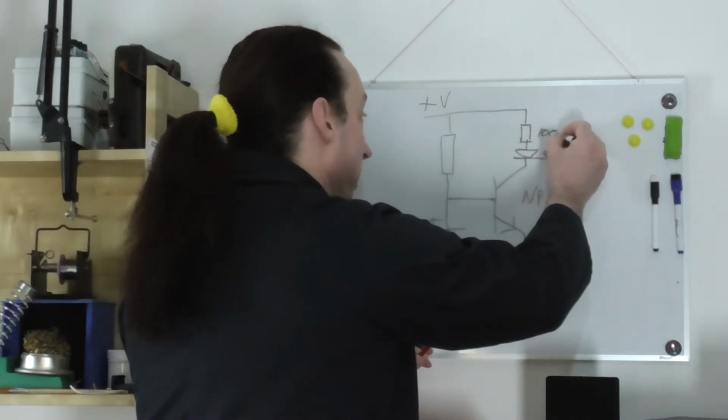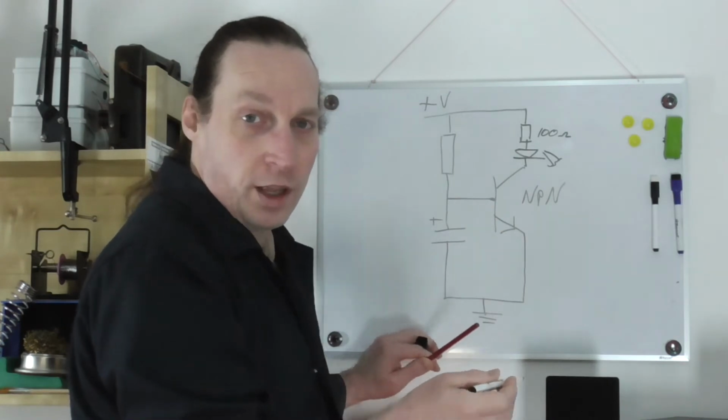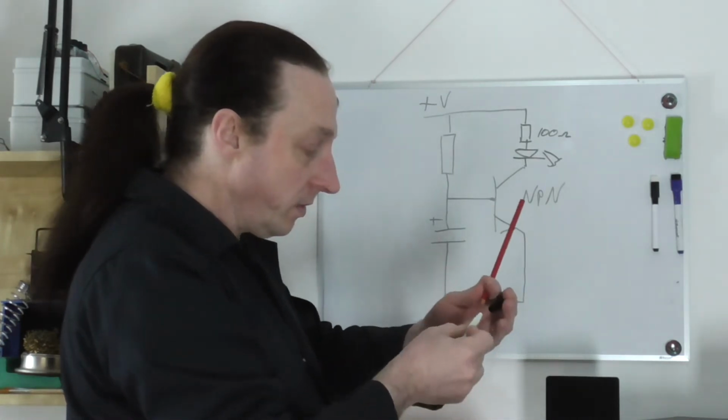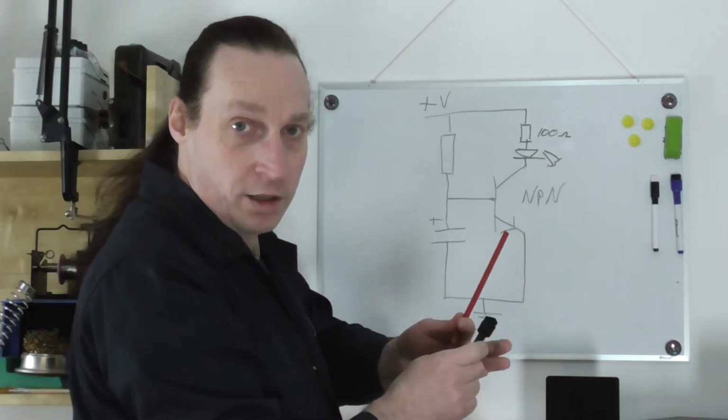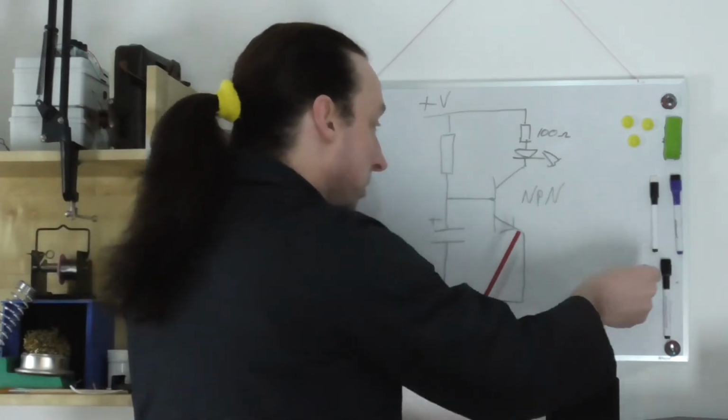I'm going to put a 100 ohm resistor in there, so that's nice and simple, so I can see then when the transistor actually turns on.